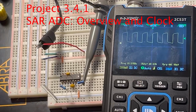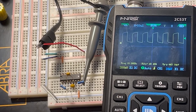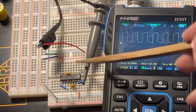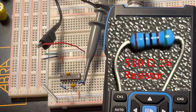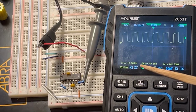Project 3.4.1 SAR ADC Overview and Clock. So this is my breadboard of the clock, which is an astable multivibrator using NAND gates. So here is the NAND gate chip. These are 0.1 microfarad capacitors, and these are 510 ohm resistors. And right now it's showing a frequency of 10.08 kilohertz.